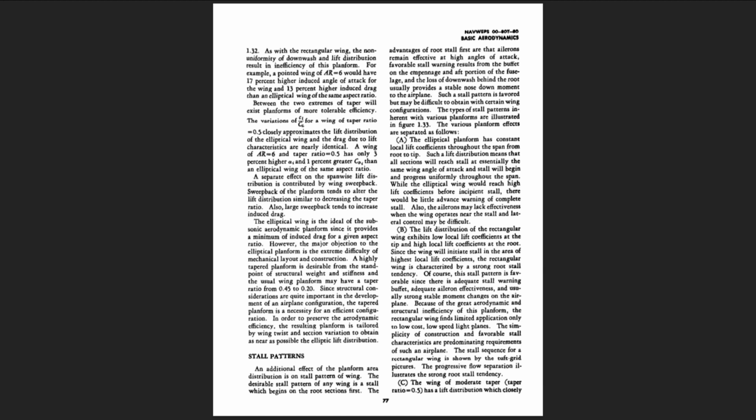If an actual wing were allowed to stall in this fashion, the occurrence of stall would be typified by aileron buffet and wing drop. There would be no buffet of the empennage or aft fuselage, no strong nose-down moment, and very little if any aileron effectiveness. In order to prevent such undesirable happenings, the wing must be tailored to favor the stall pattern. The wing may be given a geometric twist or washout to decrease the local angles of attack at the tip.